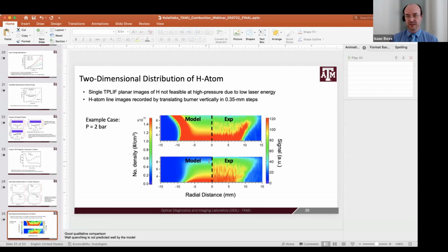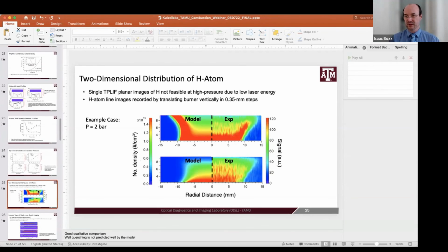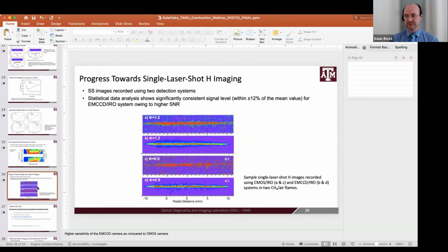Next question is on slide 26. You mentioned the EMCCD camera performs better than, I believe, the intensified CMOS camera. What's the advantage of one over the other? Well, both are intensified. What we did was we used, of course, since this question is coming from you, you know exactly, a two-stage intensifier and then a high-speed CMOS camera on the back of it.